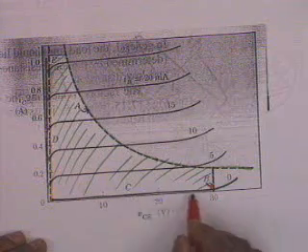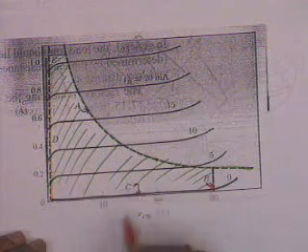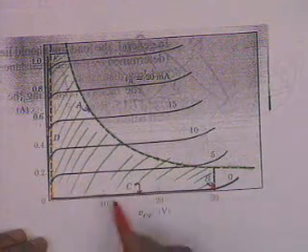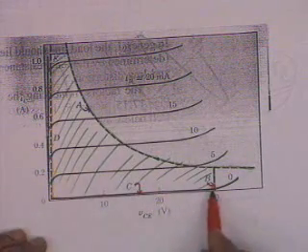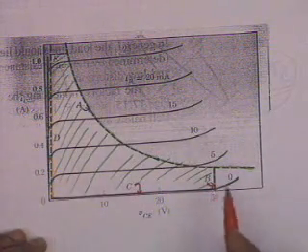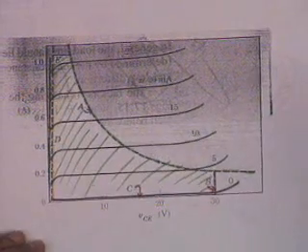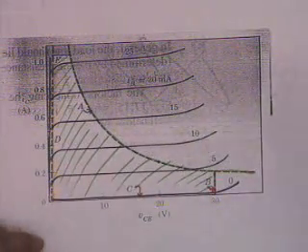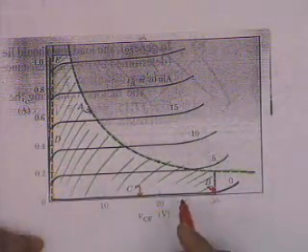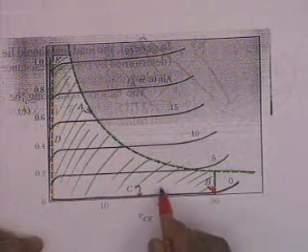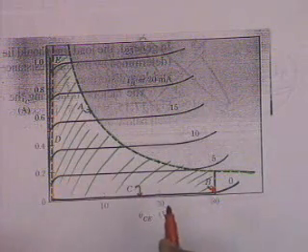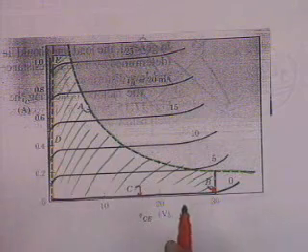And therefore the curve for IB equal to 0, this is the curve C. Alright? This determines another fence. You cannot make your base conduct less than this current. And how much is this current? Beta plus 1 ICBO. You cannot conduct less than this current.